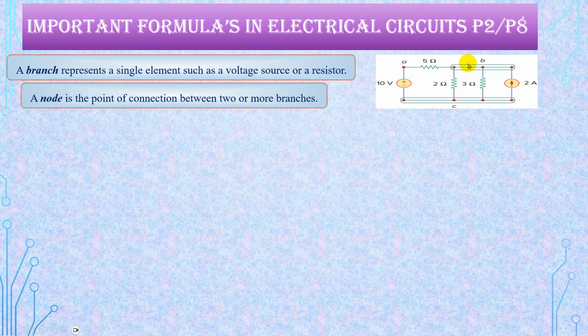There is no element in between this node and this point and this point, so this becomes together one. And here also there is no element here, so this becomes one. So all together will form one node here. So don't think here 1, 2, 3 nodes are there. No. Now coming to the downside also, between the 10 ohms resistance and 2 ohm resistance, there is no element